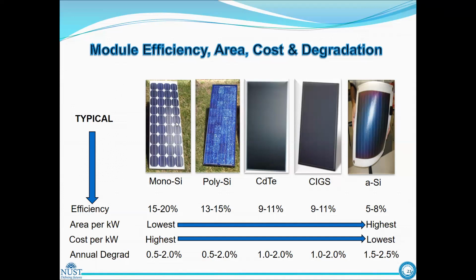Back surface is not good reflecting. It means we lost the rear side power. Yes, of course, this is true. If the back surface where we are going to install the photovoltaic module is not good, then bifacial will not be good, will not be providing better performance.